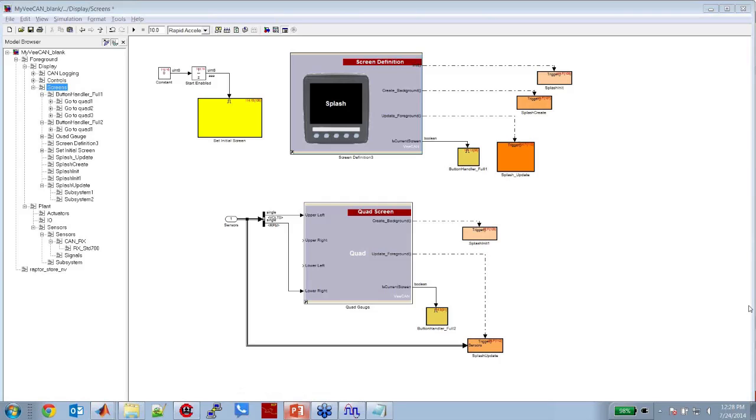Can you read DM1 messages, multi-package, and display fault codes on screen and log them? Well, you could use the 1939 transport protocol PGN read, and that would provide you the content of the DM1 message. We don't include a parser for it. The 1939 block set is geared more towards the sending side of things.